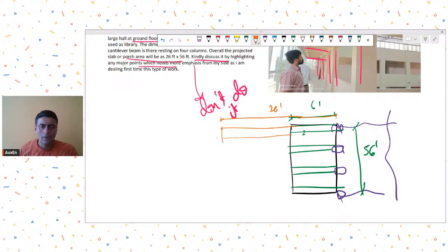And you still want it as a cantilever. So I won't suggest you to do such thing. Number one, whatever you do with this beam, your column will not be able to handle a 26 feet cantilever, which was designed to resist a 6 feet cantilever. And plus, as you are saying, it will have a library, so it will have a decent amount of load also. So don't do it. Just say no, it's not possible.